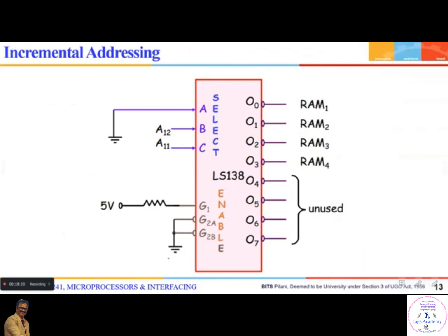So why should we take it from the microprocessor? Do we need to? No. Since it is permanently zero, you ground it directly. Similarly, you can simply ground these and use only those address lines which differ between RAM 1, RAM 2, RAM 3, RAM 4 from the microprocessor address lines.